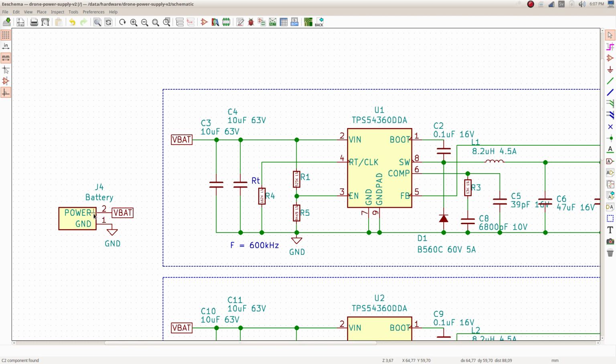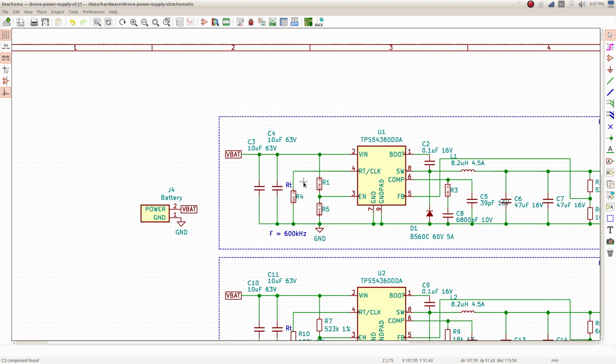So when I create those custom components, that is also an opportunity to go through every component and double check that the footprint is correct, and double check that any other parameters are correct, and the pinouts, and also just adding extra information on the actual component that you then put in the schematic. So it's like you have full control of the schematic when you make the creation of new footprints part of your integral workflow of designing the schematic.